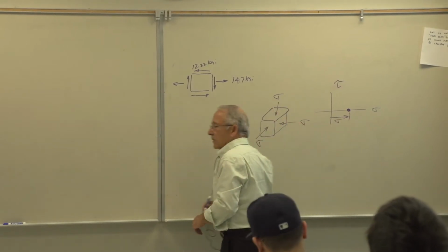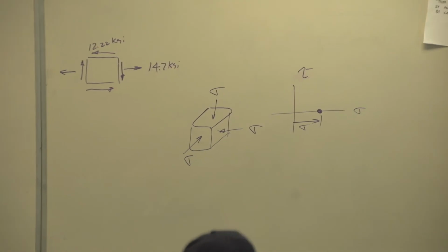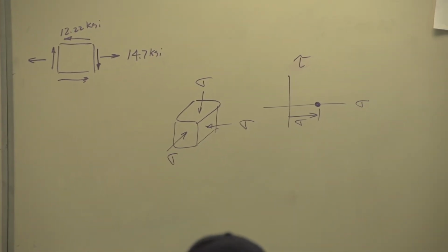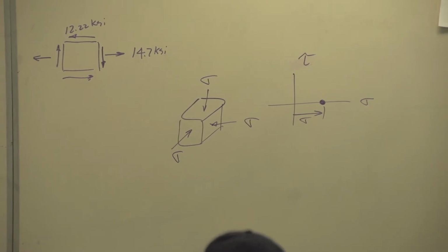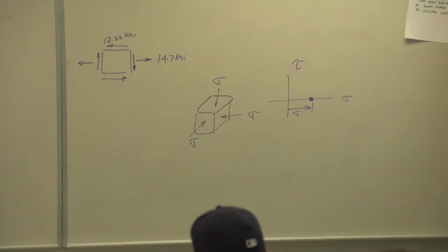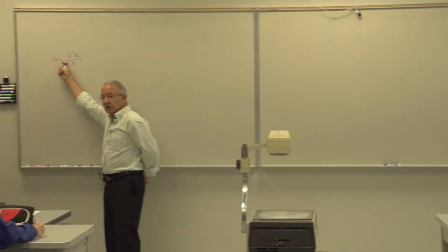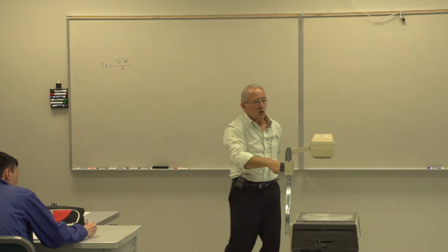That's all I get. 3 more circles degenerate it down to a point. There is no shear stress. Shear stress is 0. And if there is no shear stress, there will be no yielding. Therefore, we should not take into account all of this stress, but only that part that produces distortion.